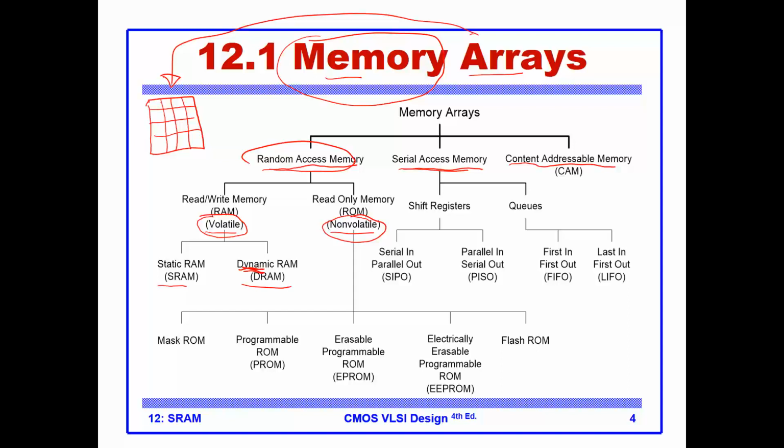So what's the use of dynamic? Well, it turned out these capacitances are tiny. So therefore, you can see that the static RAM, while it retains the data and it doesn't need refreshment and it is fast, the dynamic RAM is dense, meaning I can pack lots of information, but it suffers from data that could be leaked, so you have to refresh the data quite commonly. Okay, and because of that, it is slow to be accessed.